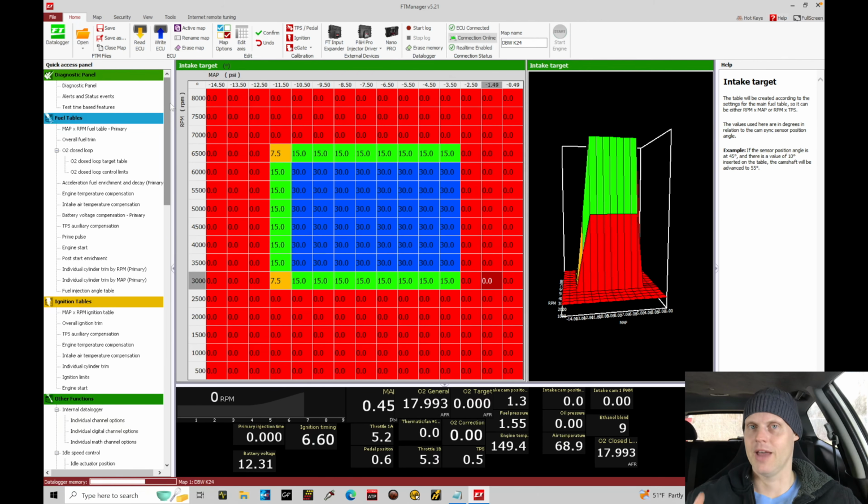Let me go ahead and fire up the engine here, so I'll make sure I'm out of gear. Now, sometimes when I get odd starting like this, and I've mentioned this probably before, I have to do a key cycle. There's some weird problem with the main relay that sends power distribution to the harness. Engine speed looked pretty reasonable as I was cranking. It wasn't skipping out and dropping out. But for whatever reason, the way that I'm controlling the main relay with the Fuel Tech does something odd, and it doesn't allow the car to fire off.